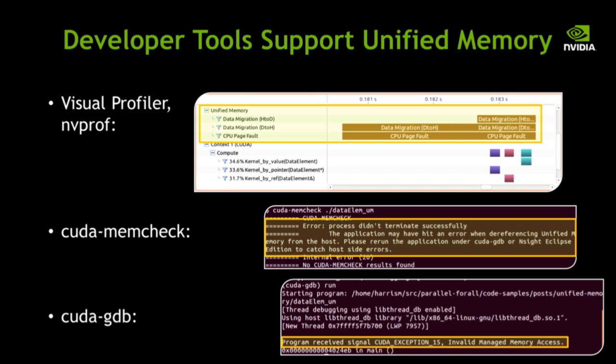Also in NVProf, it's not shown here, NVProf is our command line profiler. You're able to capture the unified memory statistics in the same way. You can visualize them in text format, or you can import them into the visual profiler.